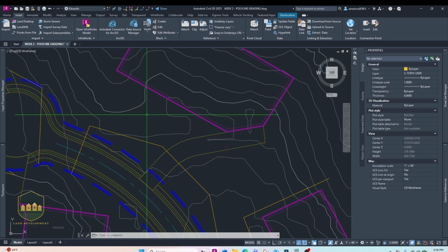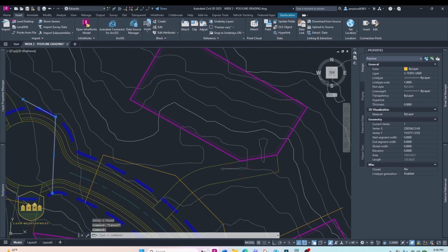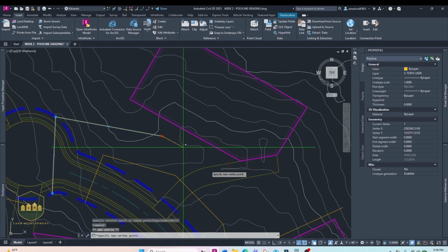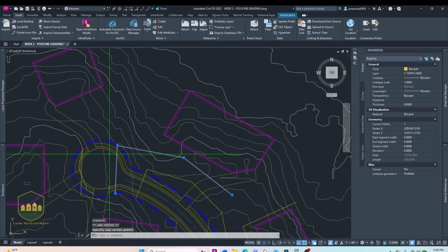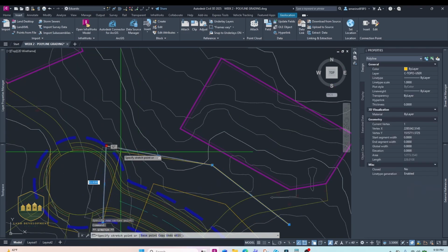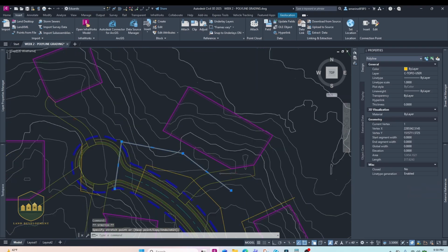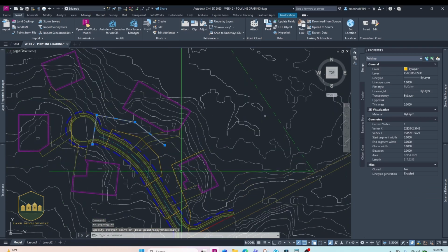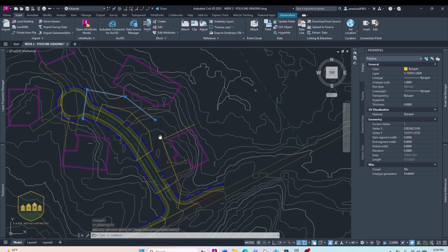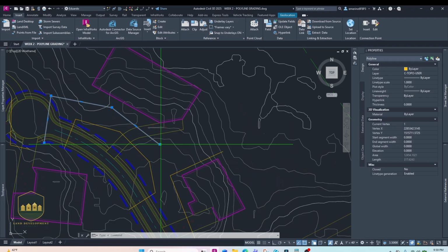My slope of the driveway is going to be less than 1%. And I want to definitively have water draining away from the house. So I want two contours to slash across the driveway to ensure that I have at least a 2% slope. It'll probably be a little bit less than 2%, but I want to go ahead and establish that.